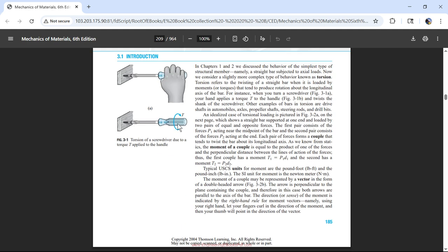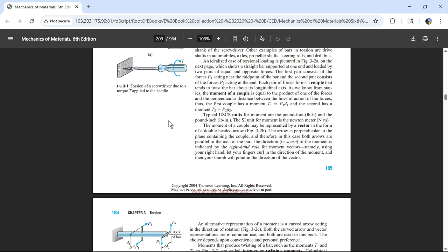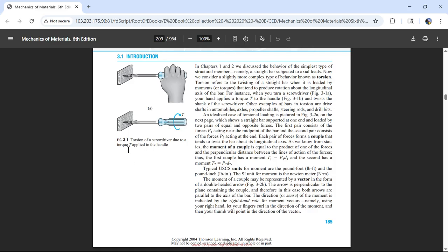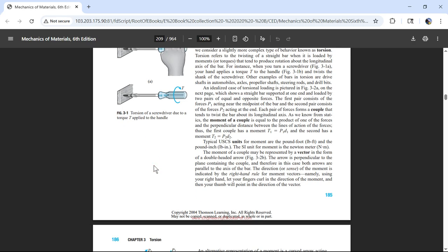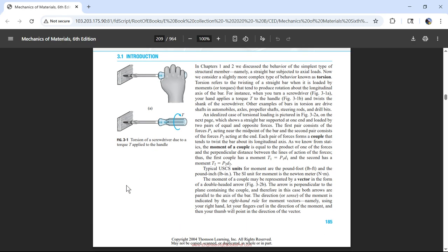If this screw isn't moving and I apply a torque, this whole shaft twists. I think we can visualize that, and that's going to be considered deformation. Even when we had our chunk of metal and we pulled on it axially and it lengthened, that's deformation. If I let go, all the molecules go back to the same location. Same thing with torques. Unless we get to that value where we mess up, when we start bending tools, when we start losing our jobs because we made bridges that fell down. That's when we're no longer in that linear range.